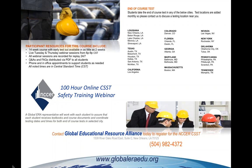And then we also have to be cautious of gases, dust, and fumes that might be produced during a welding operation, okay? Because we know it can be hazardous to us as well. We need to make sure that we're aware of those hazards and the appropriate precautions we have to take. Welding should only be done in well ventilated areas. If it's not a well ventilated area, we need to manually ventilate, or we need to put in temporary ventilation.